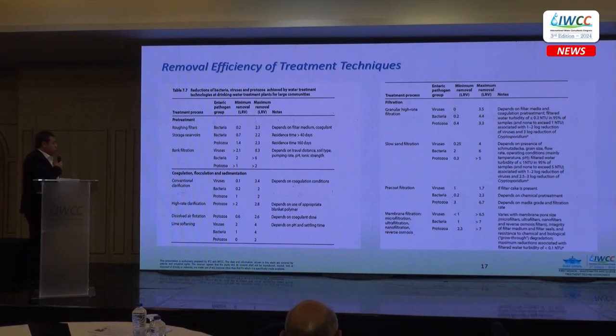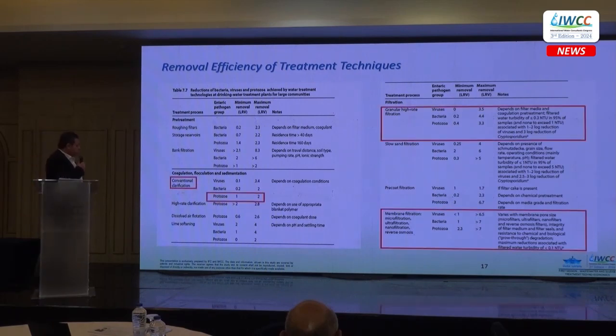This is from WHO. We could see the following: conventional clarification has very limited removal efficiency for protozoa, while for ultrafiltration we could reach up to 7 log removal efficiency. While in granular high rate filtration, the efficiency of removal of protozoa depends on the process of coagulation and flocculation.